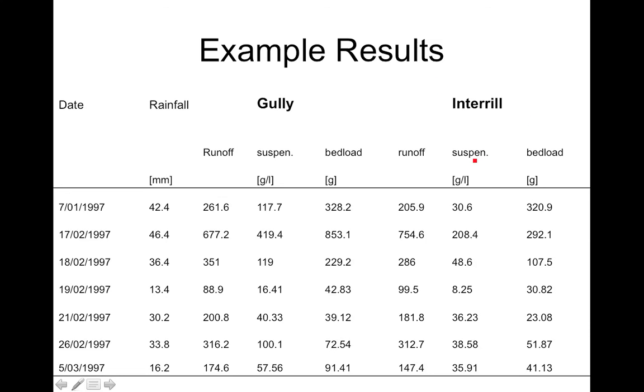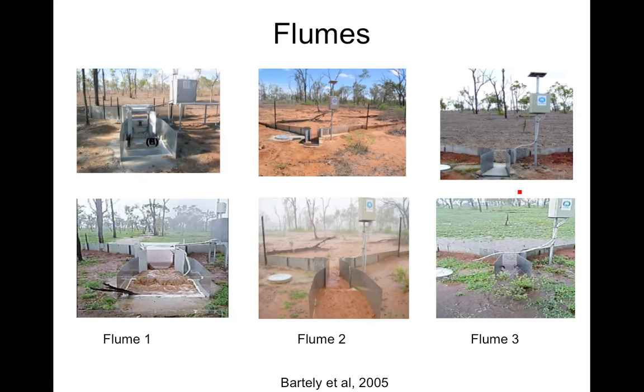You can measure also the inter-rill erosion, right? And similarly like that at different plots. Here's another example from Parsley 2005. These flat, shrubby bushlands up in, I think, northern Queensland. They have these long partial flumes, which are good for measuring sediments and erosion. You have some sort of sampler over here, which is sampling the suspended load in the flow. And these sorts of flumes here are good for allowing sediments to move through and not clog up the flume.